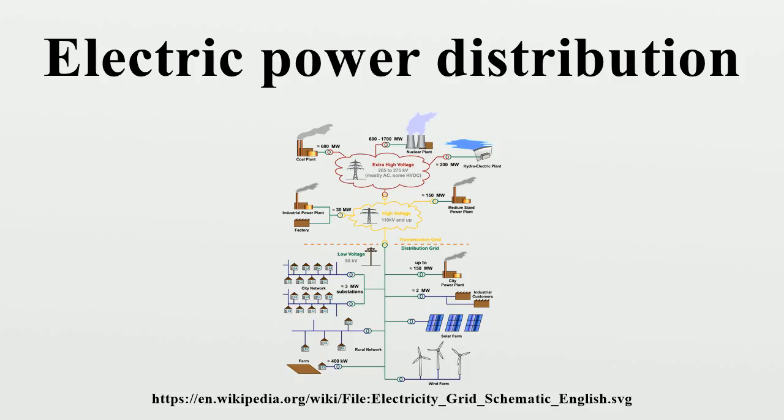The loss in a cable is proportional to the square of the current and the resistance of the cable. And since voltage and current are inversely proportional in this system, by greatly increasing the voltage the current is correspondingly reduced. Therefore, a higher transmission voltage would reduce the copper size to transmit a given quantity of power, but no efficient method existed to change the voltage of DC power circuits.